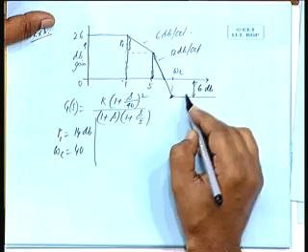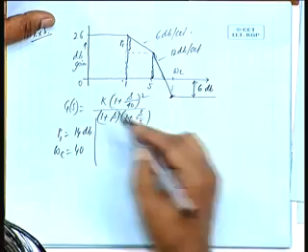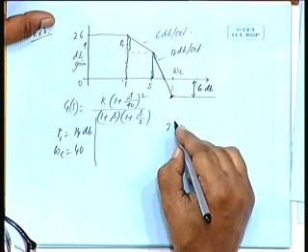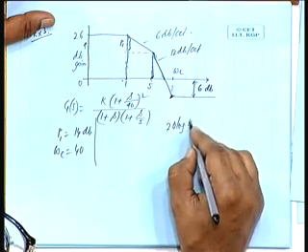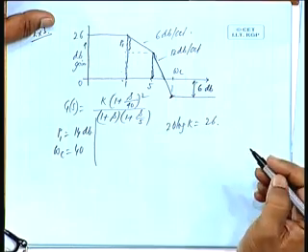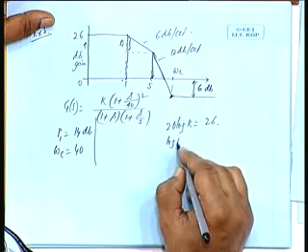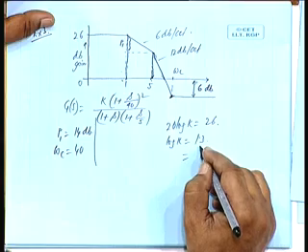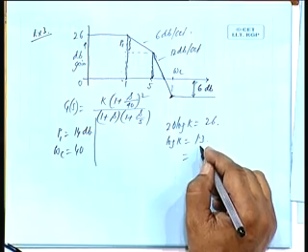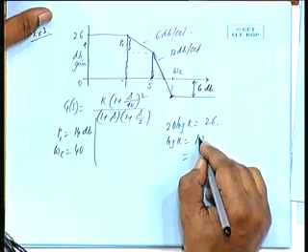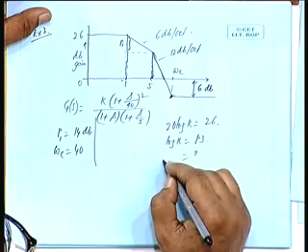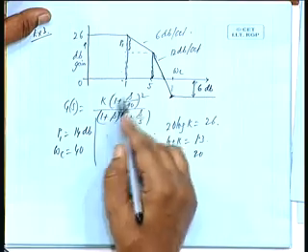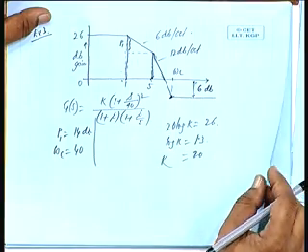From 12 dB it is coming to 0 dB. How much is k? When S is very small, 20 log of k is 26. So, log of k is 1.3, 0.3 corresponds to log 2. So, 20, is it not? So, k equal to 20. So, k is 20 and this is the function. Is that all right?